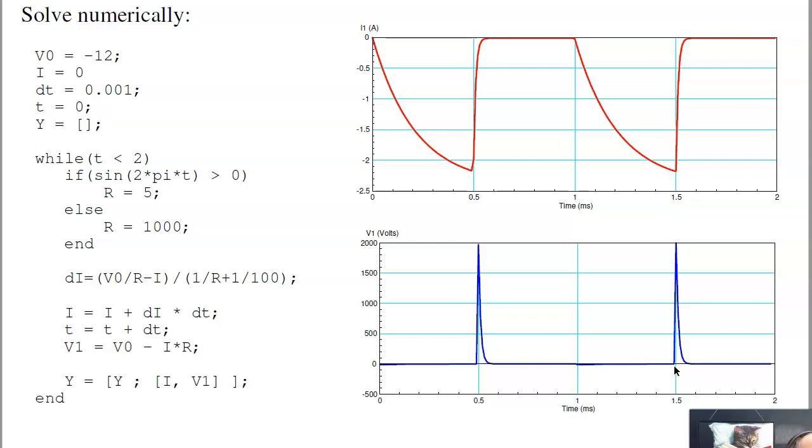That's lecture number 18 for EE206, Circuits 1. When you have inductance, again, each inductor corresponds to a differential equation. Two inductors means you have a second order system, or two first order coupled differential equations.